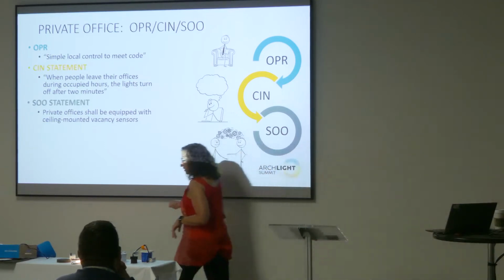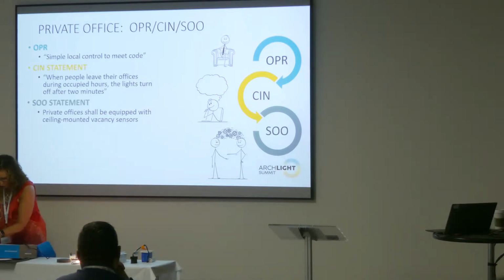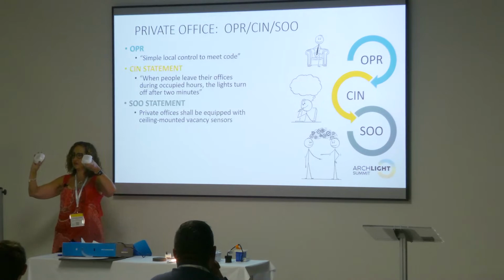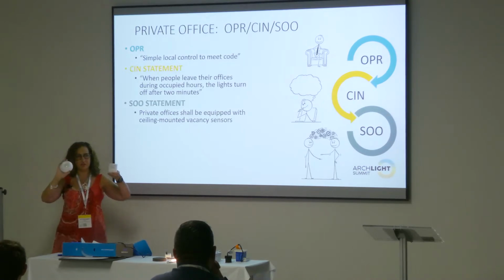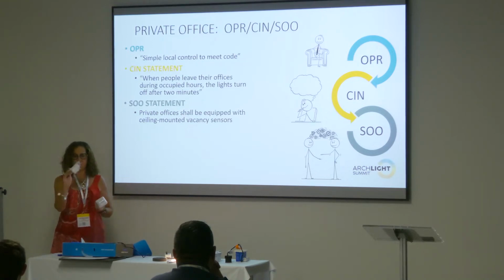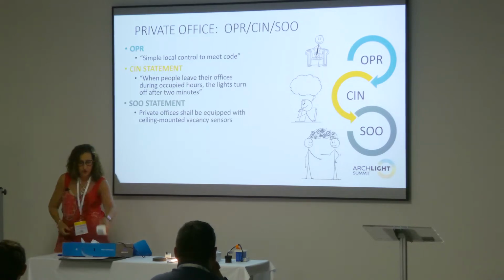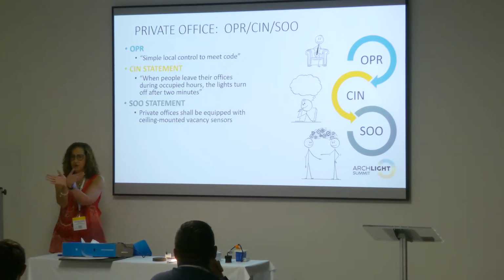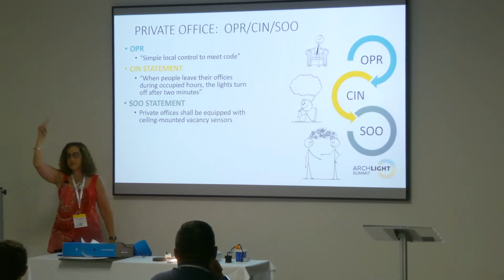Also, as it happens, switch-based sensors tend to have a much different coverage. I don't have a switch-based sensor here, but you can imagine, these two sensors are different shapes. So they have different coverage patterns and different areas of sensitivity. Now imagine that this sensor lived on here, right? We've all seen those little teeny sensors at the bottom of switch plates. It's not that we can't know, because we could look at the cut sheet and it would tell us, but the range of view that that sensor has is very different from the range of view that the sensor up there has.